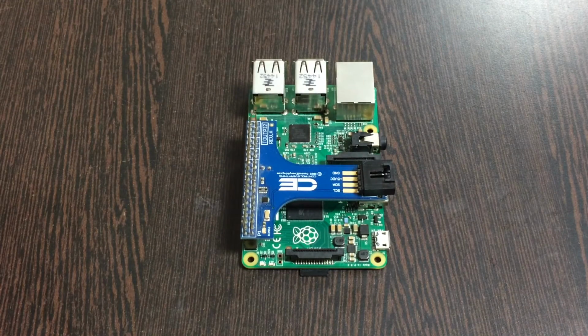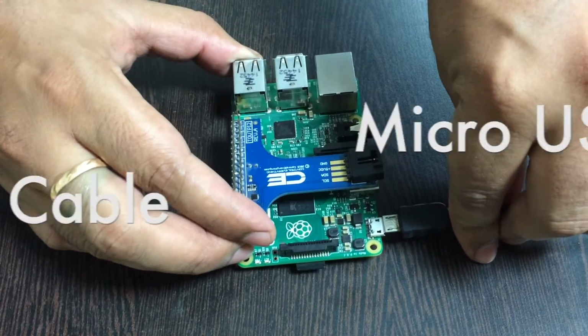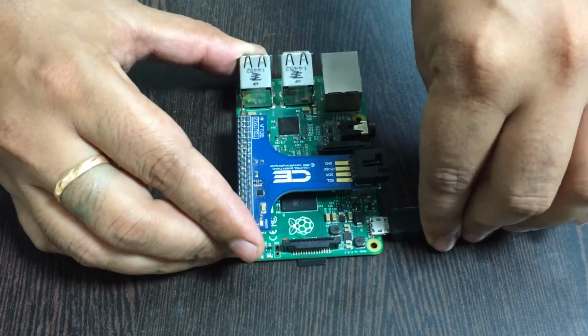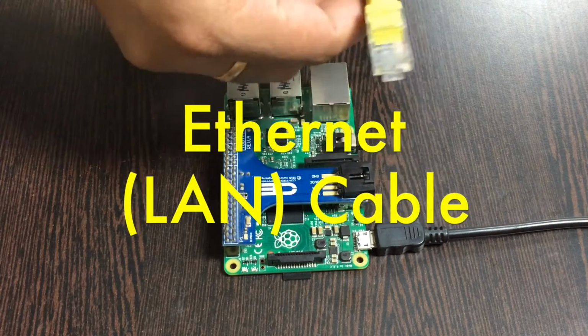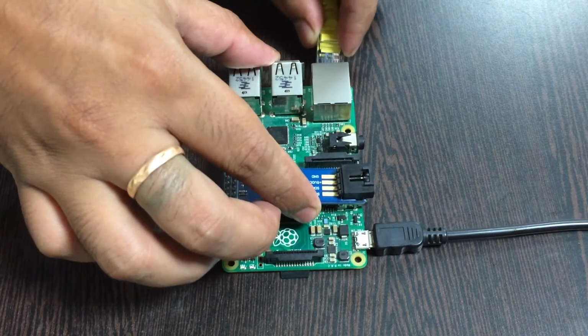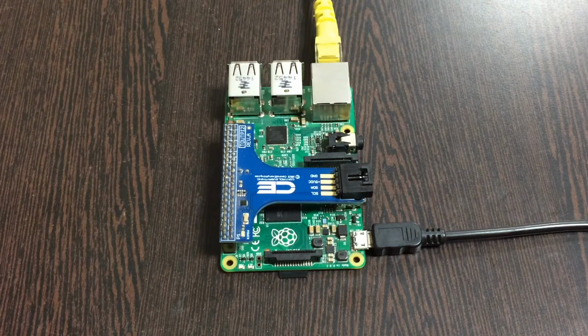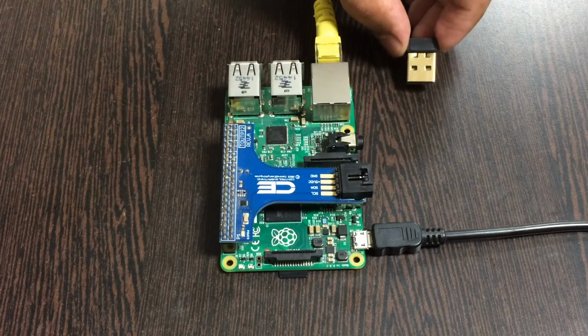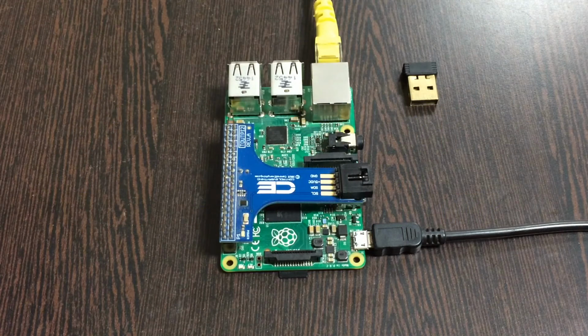Next, we need to power up our Raspberry Pi, and for that we require a micro USB cable just like that, and gently insert it over here, the power jack. And for the internet connection, there are two options. First of all, this here is an Ethernet cable or a LAN cable. Now gently insert it over this Ethernet jack and you are done with the connections part. Now for the other internet connection, we can also have a wireless nano USB adapter just like that, and you can have it on the USB port.